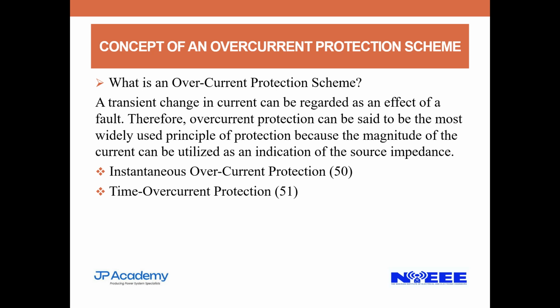But then, if we come over to time overcurrent, we can say, okay, when this motor starts, yes, the set point is 1,000 amps. The nominal current is 600 amps. But if you should see anything above the set point, which is 1,000 amps, ignore it for about 5 seconds, or depending on the motor starting time.